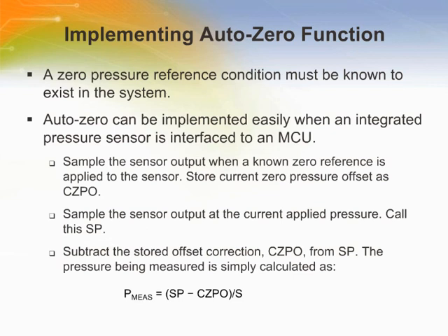This technique can easily be implemented when an integrated pressure sensor is interfaced to an analog-to-digital converter and a microcontroller. In order to use this technique, a zero pressure reference condition must be known to exist in the system. Here describes the auto zero algorithm.